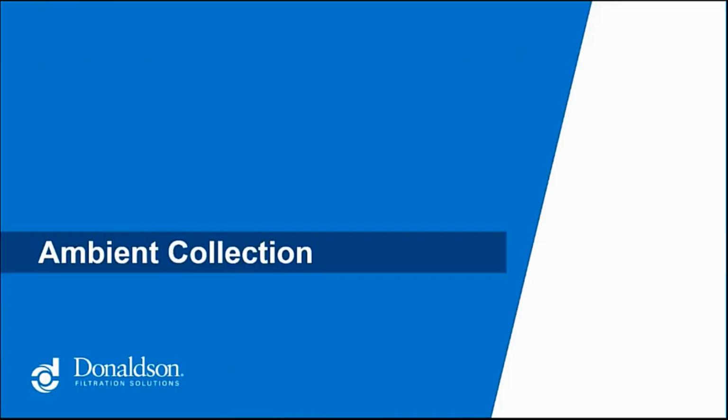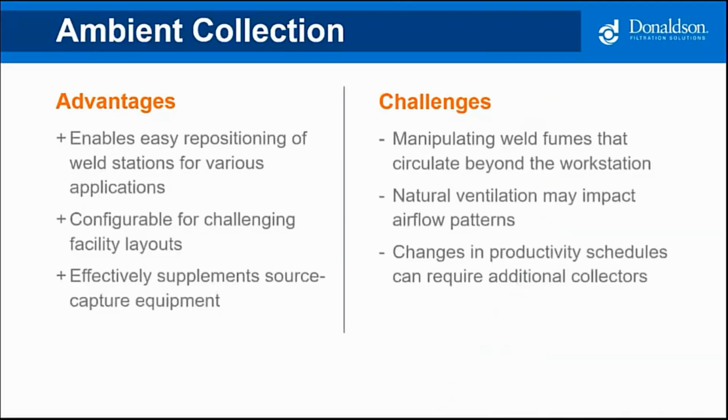Ambient collection, we'll spend a little bit of time because, as I said early, source capture, 95% of installations I've worked on have all been source capture. But a source capture isn't always the best way based on a few things. Of course, with ambient, we are taking the air as it floats up into the rafters, and we're going to circulate that air. This enables us to be flexible in our floor design. When you have a challenging floor layout, we can deal with that. And of course, you can supplement source capture and ambient as a combo to do a job effectively.